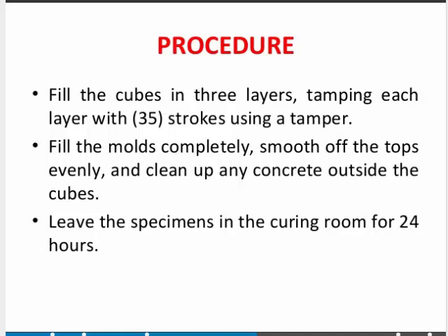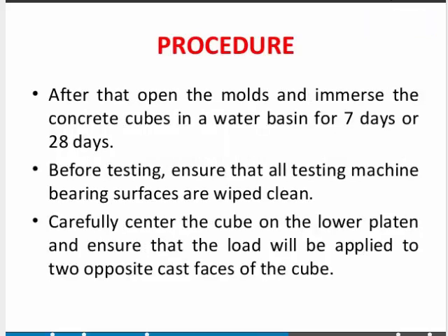Then fill the mold completely, smooth off the tops evenly, and clean up any concrete outside the cubes. Leave the specimen in the curing room for 24 hours. So this is basically the procedure. After that, open the molds and immerse the concrete cube in a water basin for 7 days or 28 days of curing, and before testing ensure that all testing machine bearing surfaces are wiped and clean.